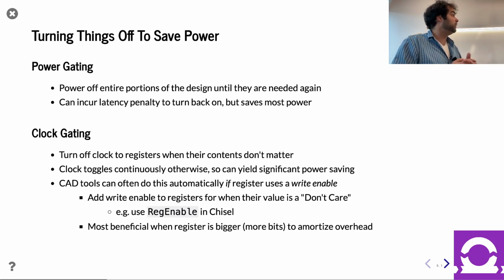And what's interesting about this is that 20 years ago, this was a cutting edge, super sneaky, cool expert trick. Now, a lot of CAD tools can do this automatically. They recognize, oh, wait, here's a register, I can do some clock gating automatically. And that way I can save some energy.